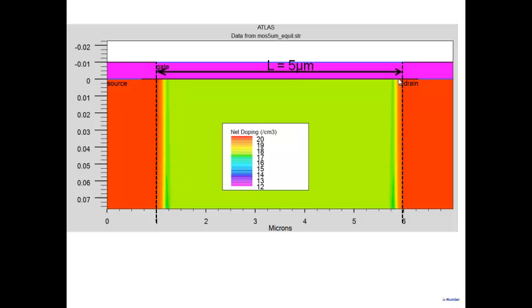If you look at this particular picture, what it shows is that from here to here is my channel length, which is called the drawn channel length. This is the channel length that I've specified, which is 5 micron. But note that this whole region is N+, and part of these dopants get into the channel. They spill over, they diffuse into the channel here. Because after implantation, you do an anneal step, which is a high temperature step, and some of them go in.